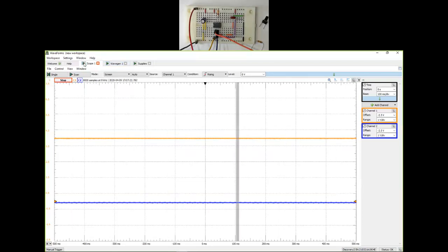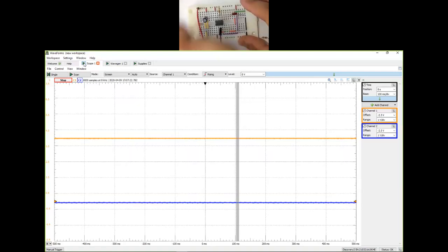So let's see. I pull out the yellow wire, which is the wavegen. Don't need that anymore. I am going to pull out the orange wire there. I'm going to leave out the output. The blue wire remains for measuring the output of the timer. I'm going to place the switch. So now what you have is pin number 2, through that orange wire, connected to one end of the switch.